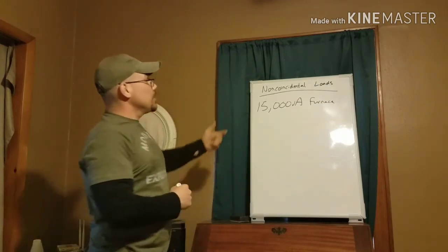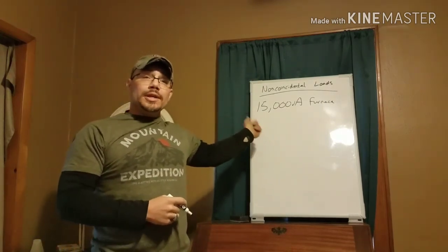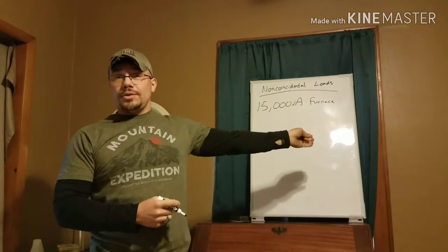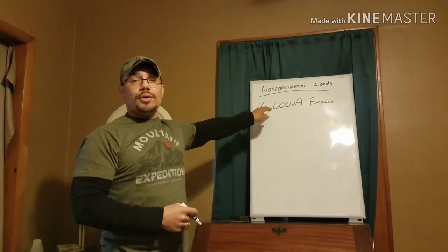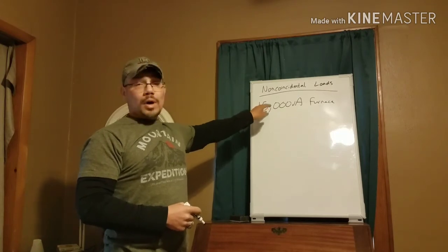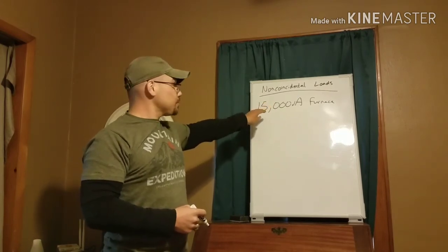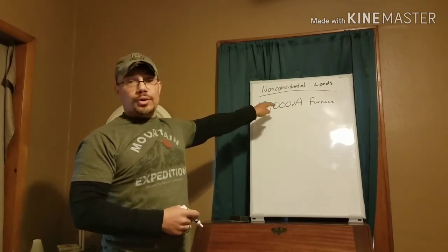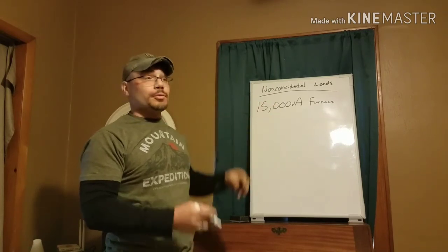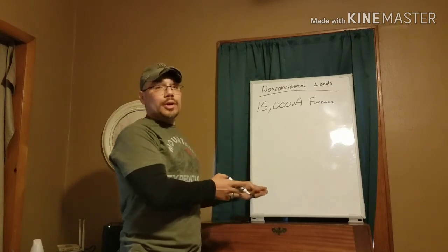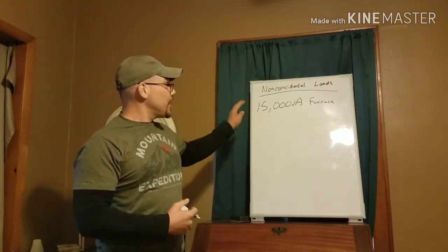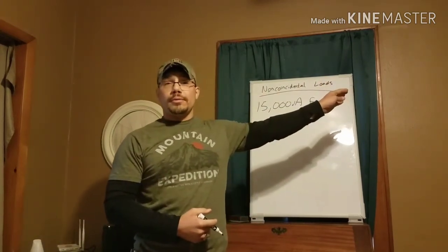Okay, we don't do anything with that except move it over to our calculation, right? Because we're going to have to use this whole load because this is a 2-wire line, 240 volt load. Okay, so it's going to be used when we're doing the ungrounded conductors, which is what we're figuring first. That's going to get moved over. We're going to use that whole thing, right?